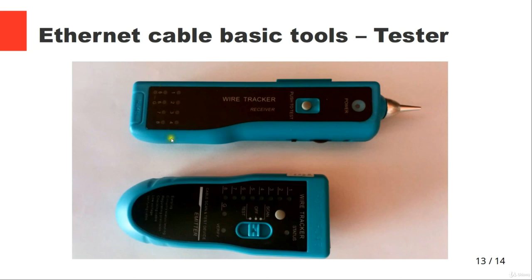So this will tell you if every core is working, if there's a short or a wire is broken, or you just wired them improperly. So it's a good rule to test the cable before connecting. Once you make the cable and terminate it, it's already there, just hanging on the one side beside the camera, on the side beside the NVR.